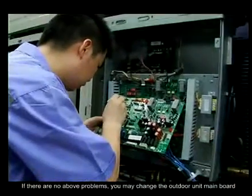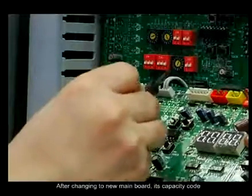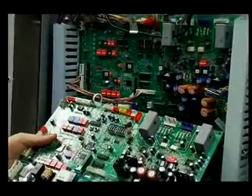If there are no above problems, you may change the outdoor unit main board. After changing to the new main board, its capacity code and address code must be the same as before.